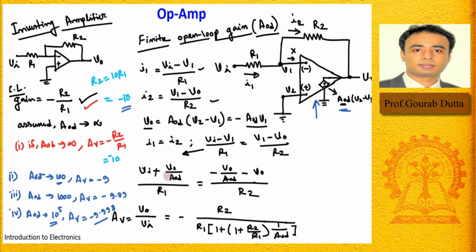Okay, so then for a practical op amp, you can use this virtual ground concept. Okay, but if in any problem it is explicitly mentioned that the open loop gain of this op amp is lower, then you cannot use the virtual ground concept, right? But in all practical op amp cases, you can assume the virtual ground concept. Fine. Okay. So if this circuit is clear to you, then let us consider another type of inverting amplifier where